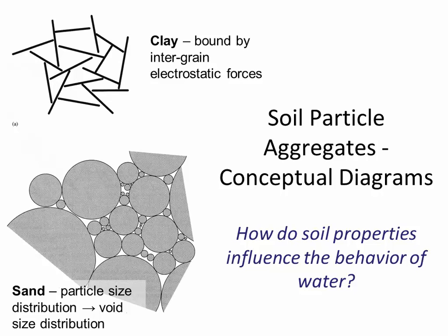If we have a tank of water and we put in a glass tube, you'll remember that the water will rise up in the glass tube because of surface tension, because the water wants to be in contact with the glass tube. It'll rise up a little bit naturally. But if we have a very small diameter tube, then the water level will rise much higher, because the surface tension forces pulling the water up in the glass tube are greater than the weight of the water above the water line inside the tube. So this was called surface tension.